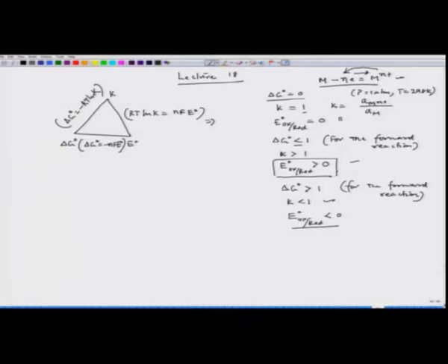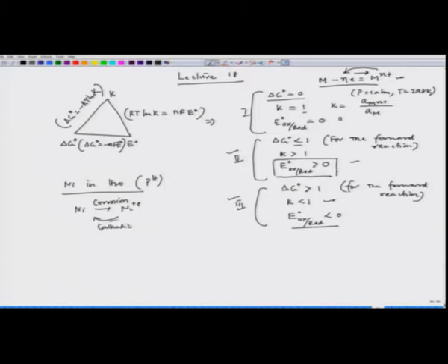So, the corrosion as well as metal deposition are happening at the same rate. So, these three situations, this is situation 1, this is situation 2 and this is situation 3. In fact, situations 2 and 3 would guide us whether the corrosion would take place or not. Now, when we talk about a normal system, let us say nickel in H2O of certain pH, nickel might get oxidized, that means nickel can form nickel ion. So, that means it is corrosion, or it can go back and form nickel. So, that becomes my cathodic reaction or less corrosion.